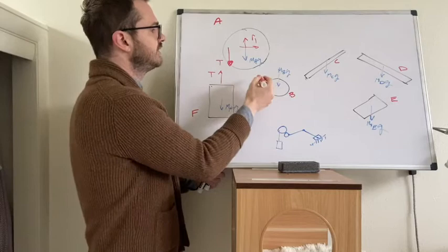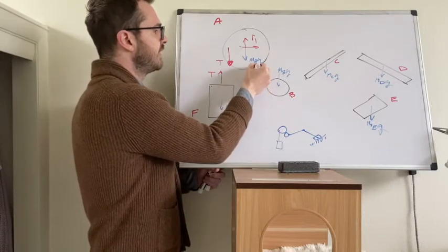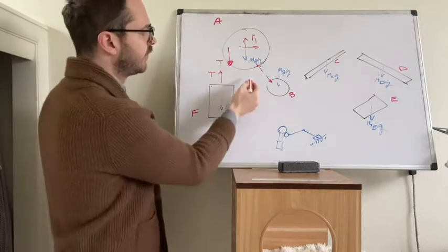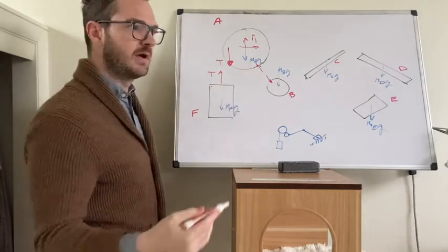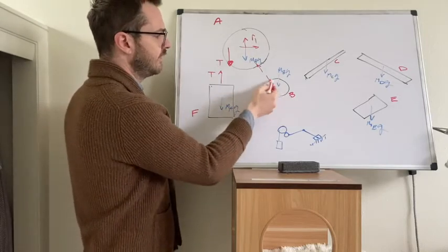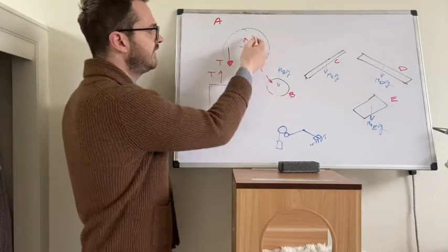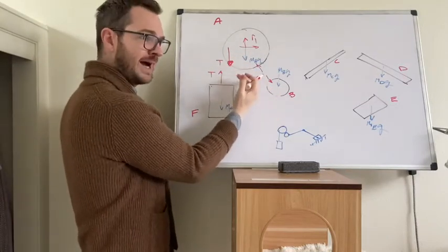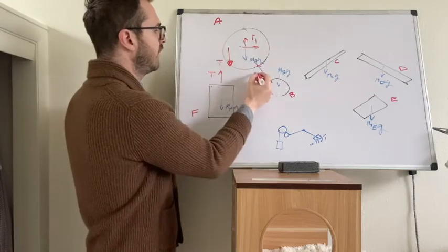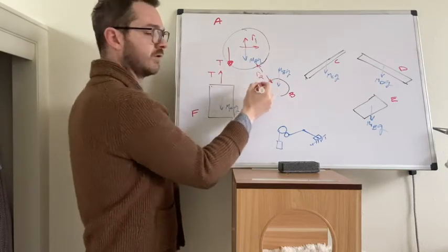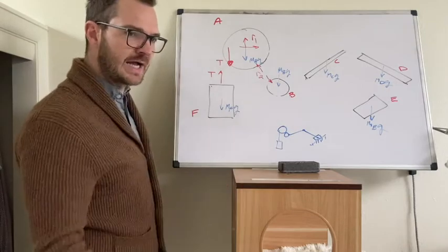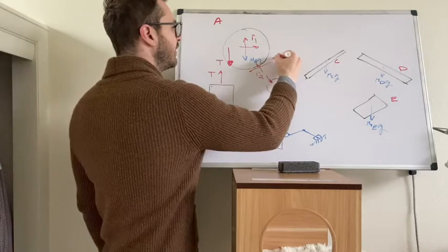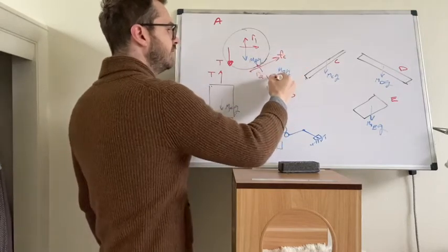Now, if they're being pushed against each other, that means that there is some force between these two. So this force between them is akin to a normal force. Consider that with this lower disc here, this big disc is prevented from translating into the lower disc, right? So the lower disc pushes back. So this was R1. Let's call this R2. Because again, it is a reaction force, it's a normal force. Along with this R2, there is going to be some Coulomb friction.